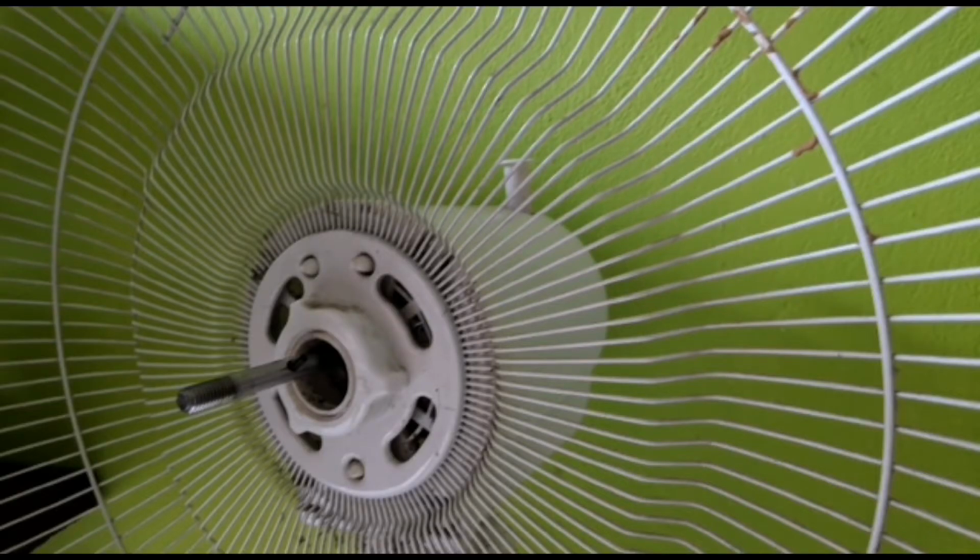And next we are moving to the motor. For persistence of vision, the setup is required to rotate at an RPM of 1800 in order to achieve 30 fps. Speed above 1800 RPM is also applicable. Actually, here we use the motor of a pedestal fan due to unavailability, and we removed the wings of the pedestal fan and placed the 3D display with the frame here. And this motor works at 220 volt, and it is able to achieve 1800 RPM.